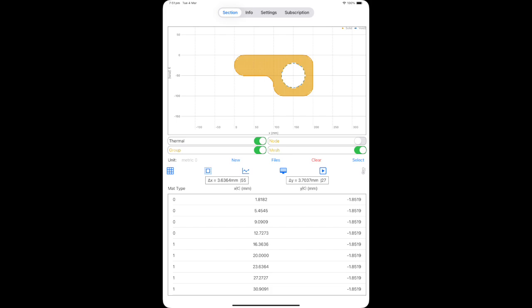Double-tap the mesh text in the Mesh Toggle button to show the material number of each mesh. If the mesh number is shown, then any void with material number of 0 will be selected by the band. To select only material number for non-void elements, double-tap the mesh text in the Mesh Toggle button to hide the material number. Tap on a point on the chart and start to create a band around meshes for the material